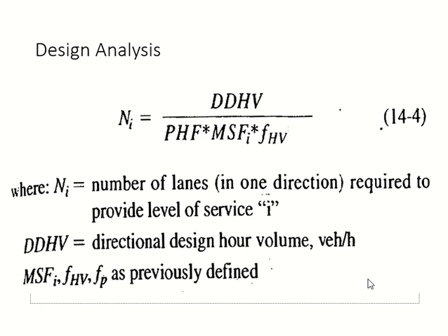But when designing the highway, shouldn't we always aim for level of service A? No. Why not? I'll come to it. I asked the question first, right? Answer me first. Which value will change N for any level of service? Volume? DDHV will not change. If you tell me I want level of service A or B or C, demand volume will not change. Which value changes according to level of service in the equation? Maximum service flow rate.